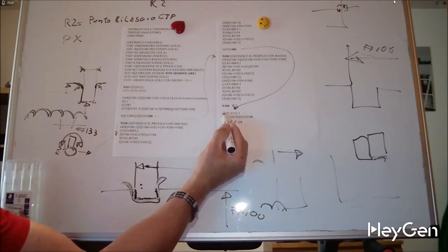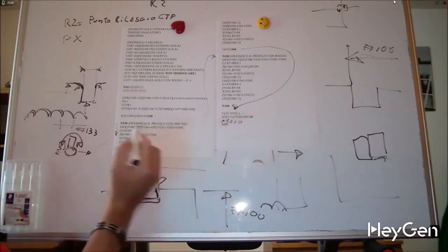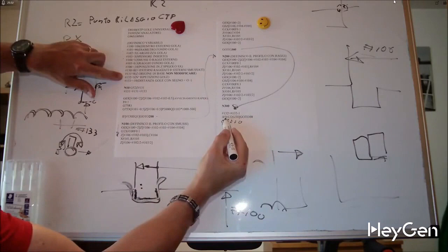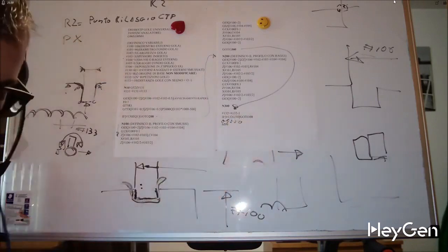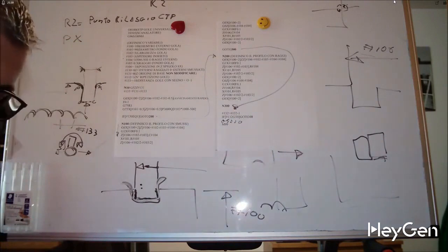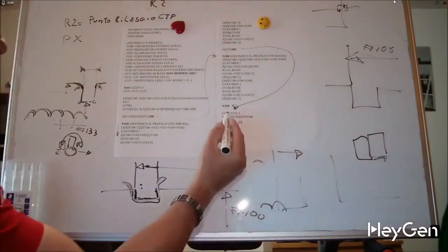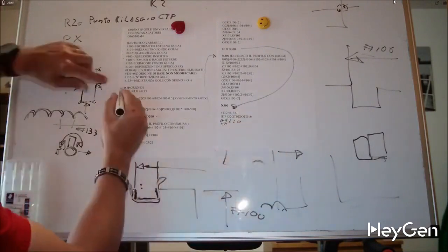I take hashtag 132 and subtract 1 from it. So hashtag 132 is indeed my repetitions. If hashtag 132 is greater than 0, I go back to block 10 and execute it with #131.